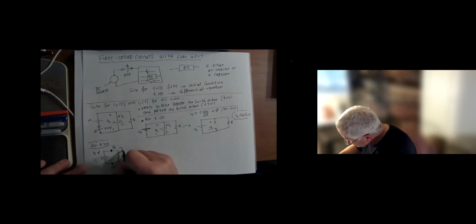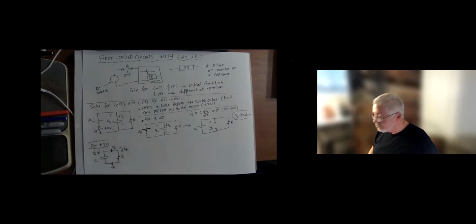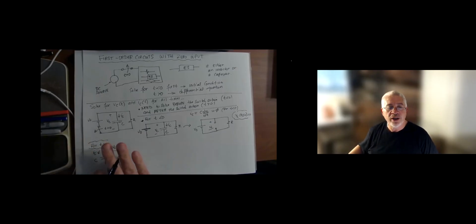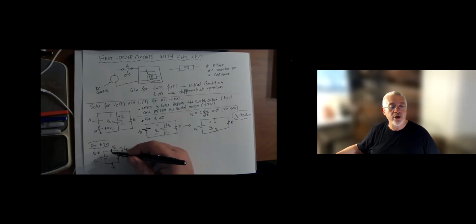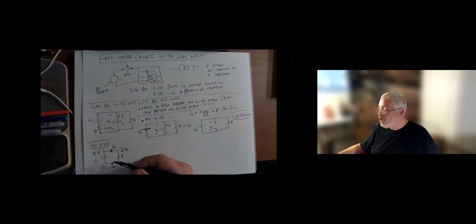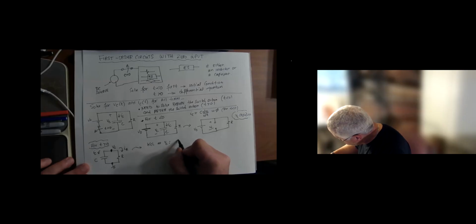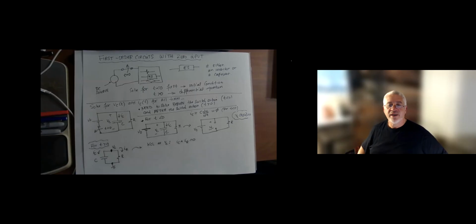I'm going to put a resistor on my current, and call it IR. This is the standard nodal procedure like we've done before: select my nodes, select a reference node, and label the other node. In this particular case, it's only a pair of nodes, so the reference node is here, and this node is VC. Now I'm going to do KCL at VC, which is IC plus IR equals 0. That's my KCL equation at VC.